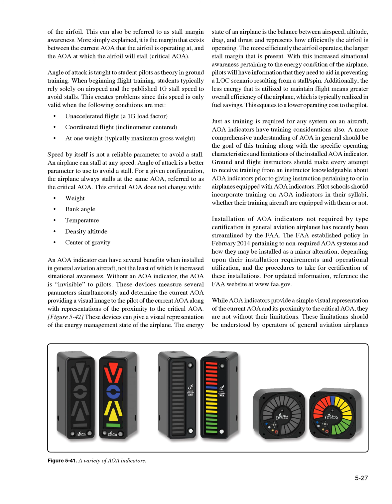Angle of attack is taught to student pilots as theory in ground training. When beginning flight training, students typically rely solely on airspeed and the published 1g stall speed to avoid stalls. This creates problems since this speed is only valid when the following conditions are met: unaccelerated flight, a 1g load factor, coordinated flight with the inclinometer centered, and at one weight, typically maximum gross weight.